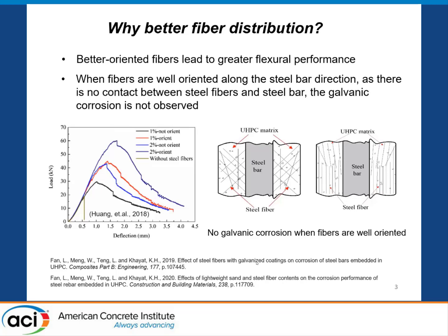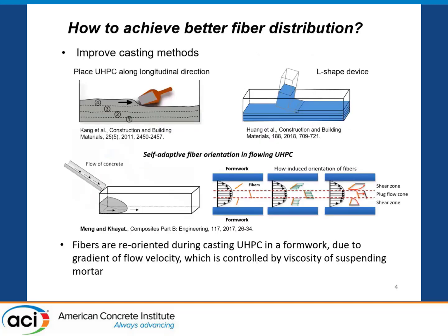Then I have another follow-up. Do you consider using a defoaming agent? In our mixtures, we actually add some of what we call an air detrainer admixture. It's a kind of defoamer. So it's better to use that to reduce the air content if you want lower air content in your mixture.